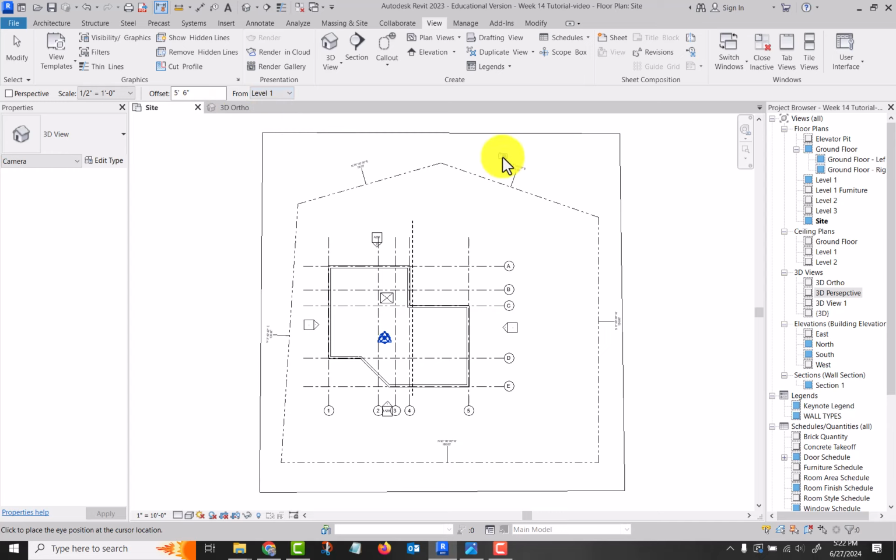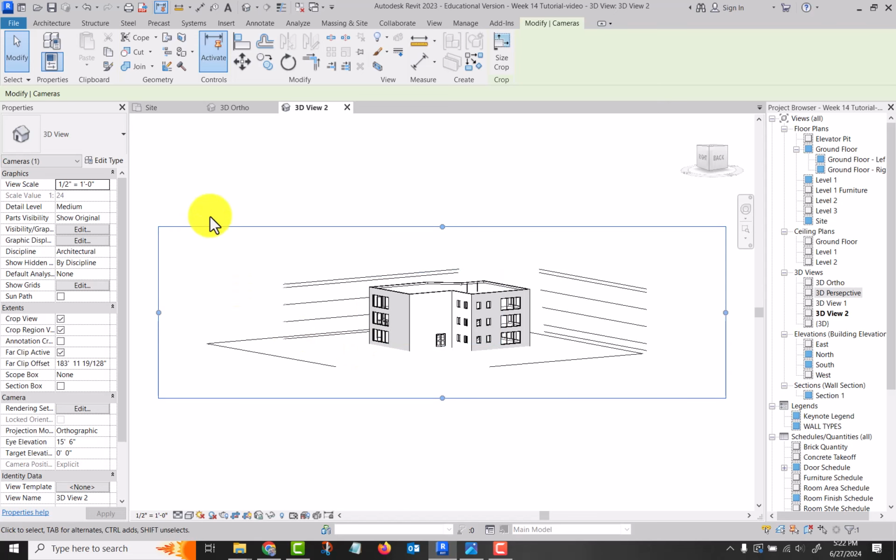And I'm going to come back here and place the camera, and then drag my mouse out, and that gives me a path and a target. And the target is just that. It's the target of the view. And if I change my height here to 0 ground floor before placing my target, then it sets my target location. And so now I've got my camera out here at a set height and my target back there in the back.